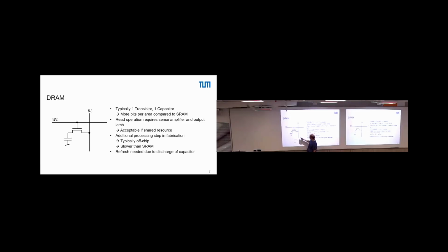If we close the switch, in that case, well, our voltage will go a tiny little bit up, and then most likely down again. So what we need again is, at that position, a sense amplifier that senses this tiny peak, and then amplifies it to the full VDD ground level. So far, makes sense?